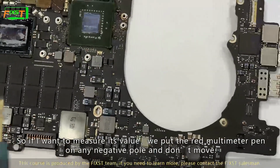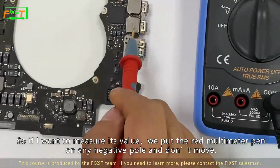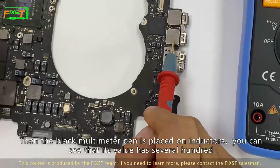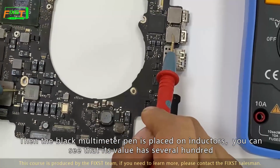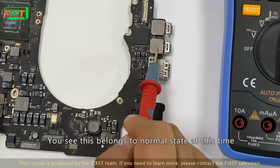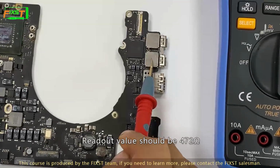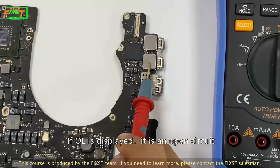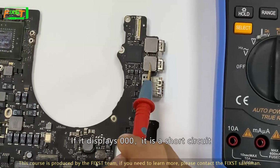So if I want to measure its value, we put the red pin on any negative pole and don't move it. Then the black multimeter pin is placed on the inductors. You can see that its value is several hundred. This belongs to a normal state at this time. The value should be 472. If OL is displayed, it is an open circuit. If it displays 00, it is a short circuit.